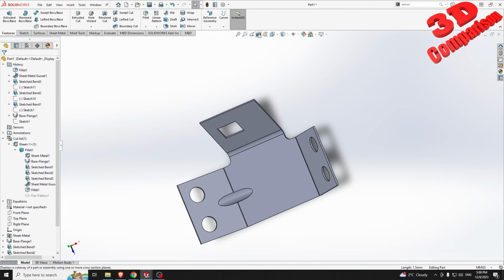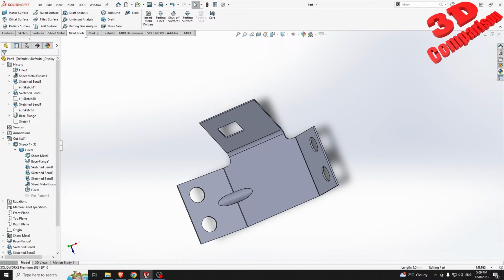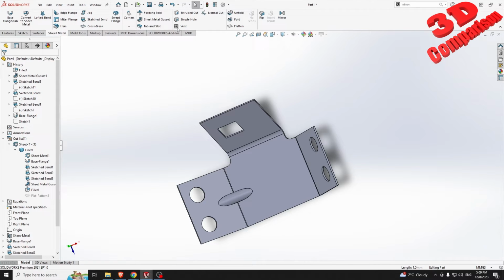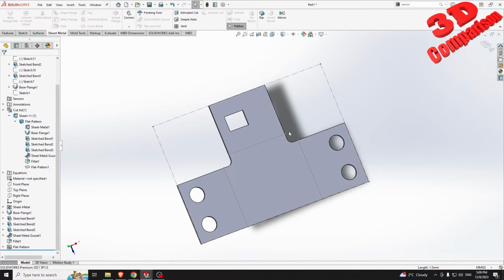And we're gonna see that if I will have this folded and unfolded, flatten, we're gonna have that radius directly defined within the cut over here. So we have the base flange, but only afterwards we're gonna have the fillet. So this can cause some problems on the manufacturing. Therefore, you can easily embed existing fillets. In this case, this was positioned over there.